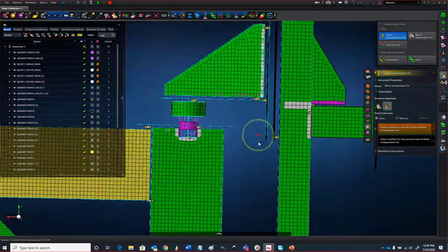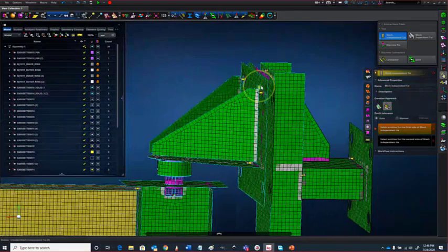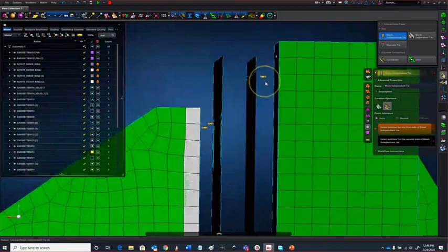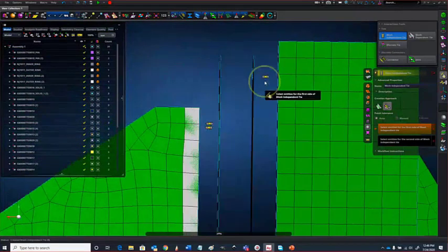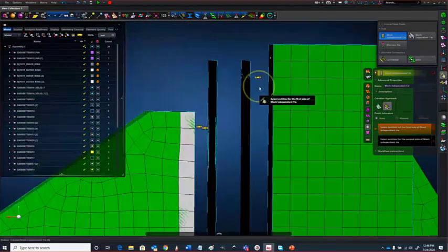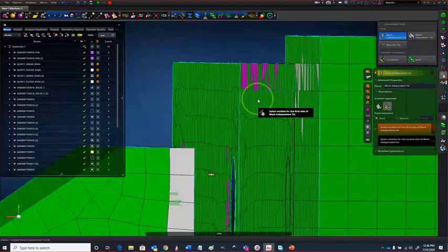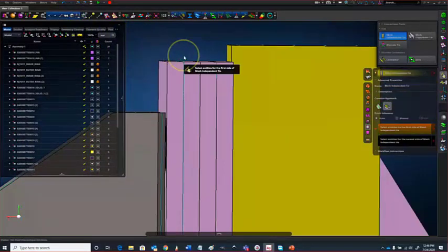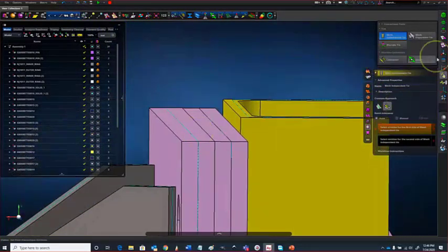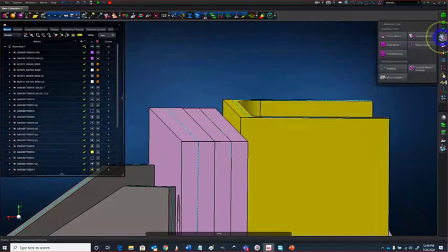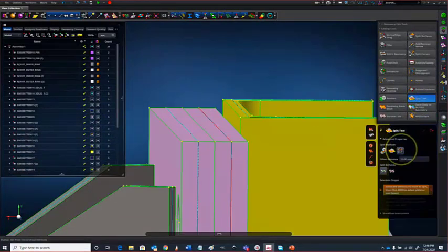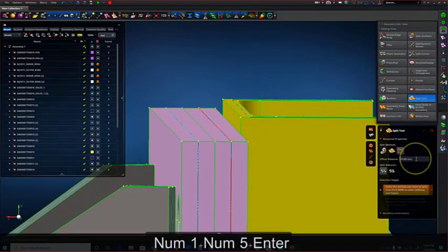And there we go. Now, of course, you may want to split the plate to have nicely, evenly spaced elements so that they're not jagged like this. So one way of doing it is to utilize the solid that we actually have available and use the split tool over here with the offset option. And let's say we want a weld of 15 millimeters thick.